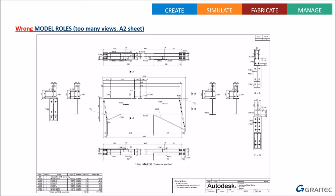One last example, here's a rafter. Again, I've called it beam. I've deliberately set every model role wrong in this part, and not just the main part. So I've got loads of views there. How can I have 4 end views when I've only got 2 ends? That doesn't make much sense. And I've got top and bottom views there, really hard to understand.